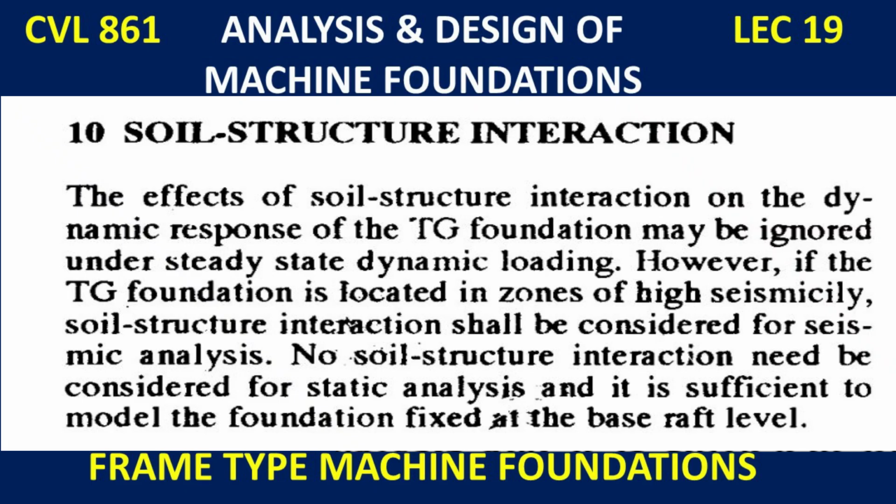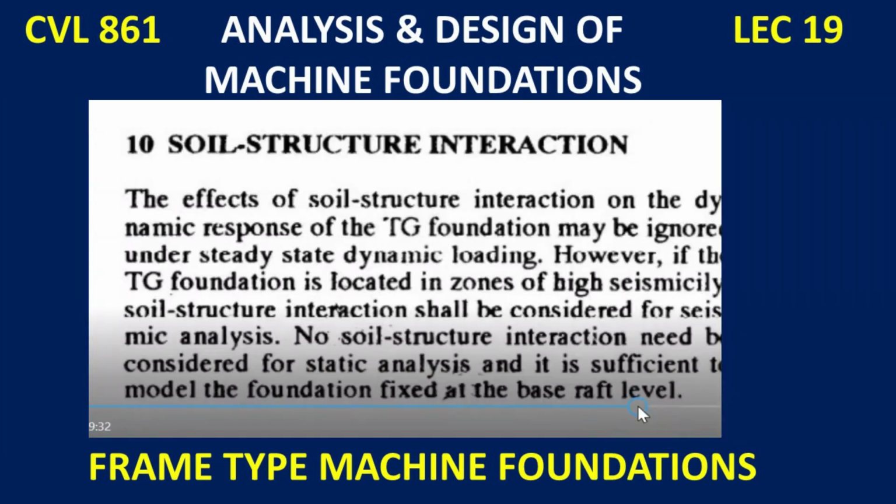It is sufficient to model the foundation fixed at the base raft level. So in general, we just model the frame, the columns, to be fixed at the top of the base slab. So that's enough. The soil parameters, the stiffness of the soil, in that case does not enter the picture, because we have chosen a very stiff, very thick base raft. So the soil becomes less important.